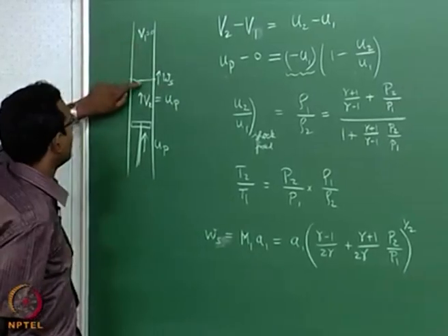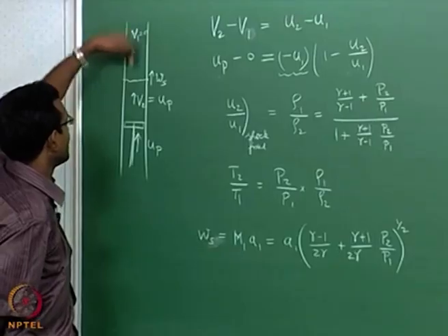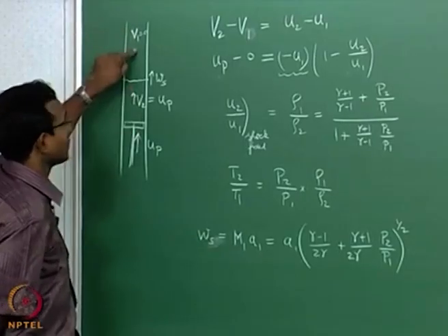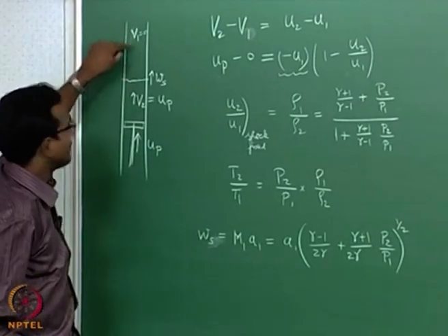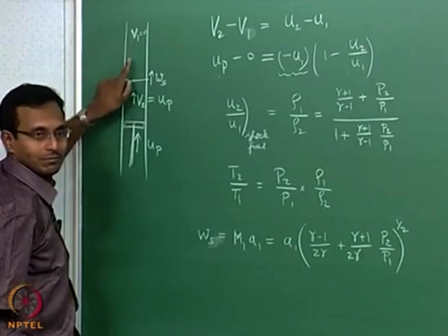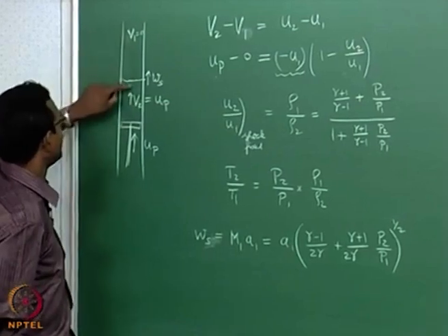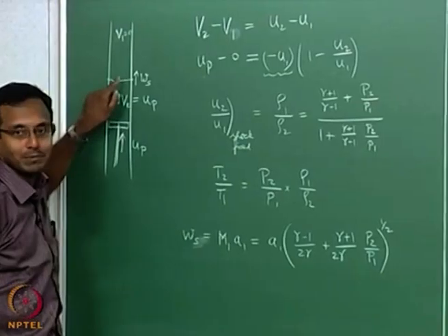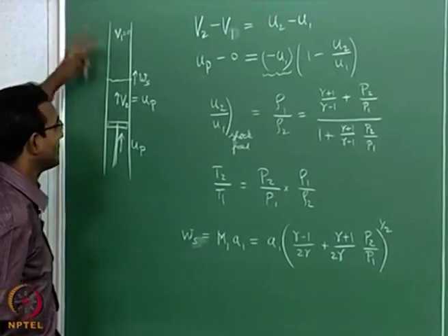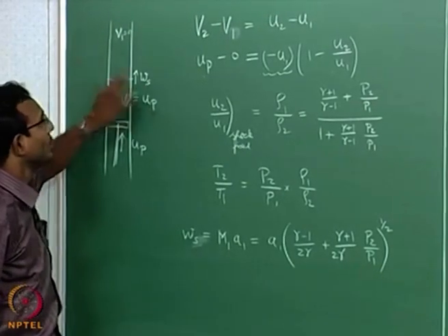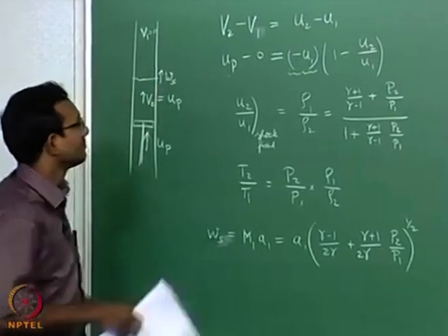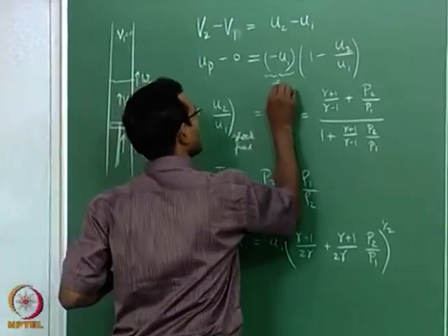Because of that, with respect to shock, the incoming gas velocity will be equal to the shock velocity with respect to that gas. They are standing, my bus is moving. Equivalently, I am going to see that they are coming in this way with the same speed as the bus, same relative example. So, that will be minus U1 will be my Ws. So, this is going to be my Ws.